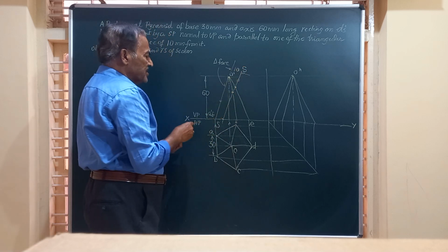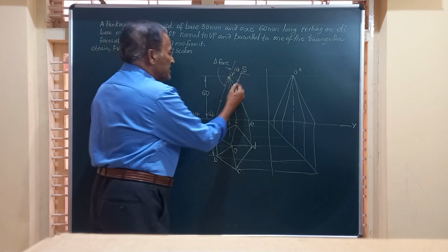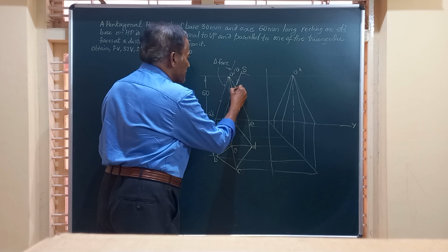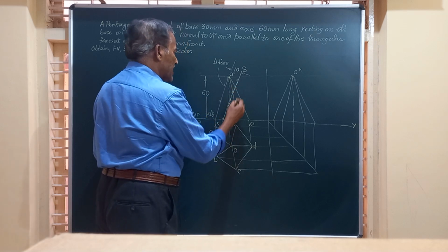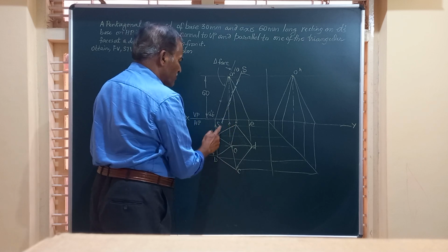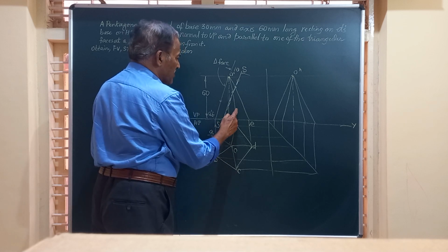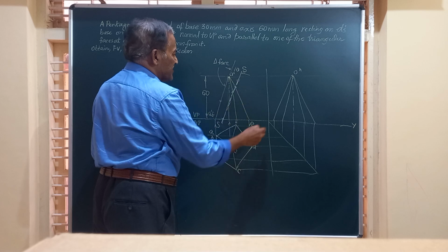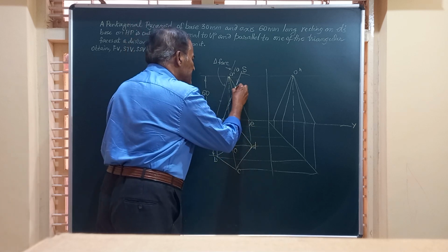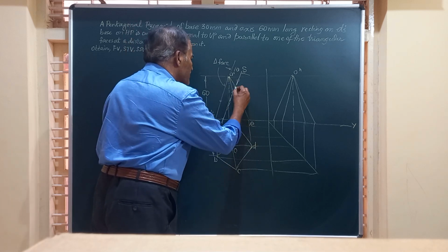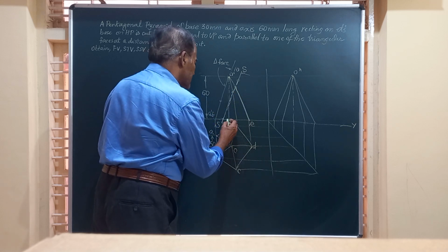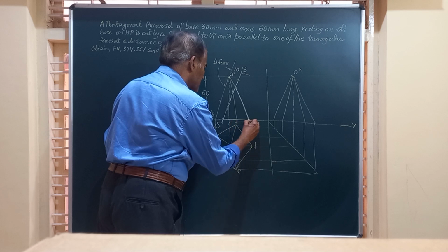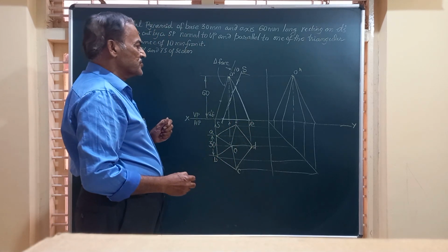And friends, this is being cut by this section plane, which is parallel to that, and cuts this solid both at the bottom face and also along these edges. So let us retain that part of the pyramid which is to be retained for drawing the sectional views.